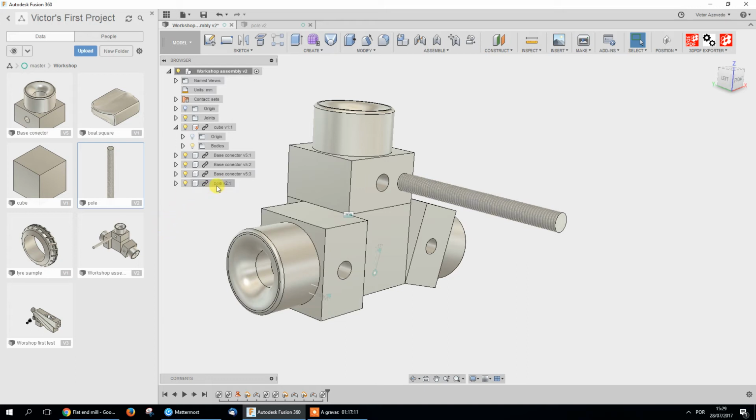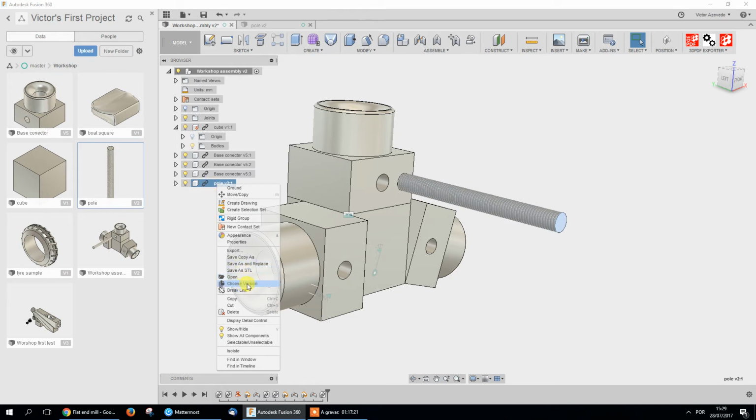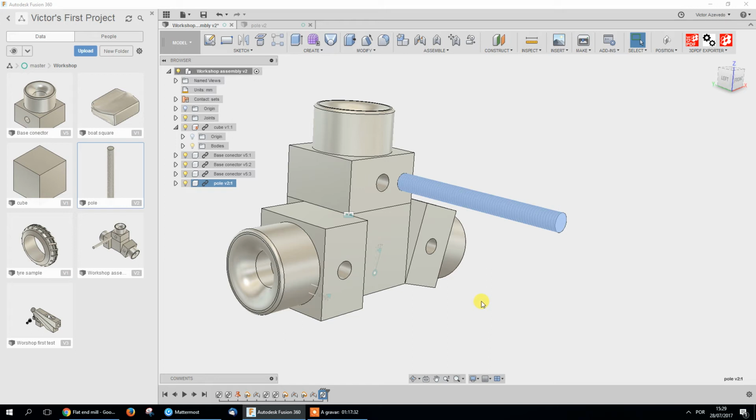to this. To update to the new version, you can click on the warning up here, or right click and get latest. In this case, it doesn't show up, but you can use get latest. Okay? There are 2 options. Also, 3 of my pieces are transparent. That's because you double clicked on one of them. Try to escape. Usually it means when you enter the part, double click the component, it will try to edit only that component.